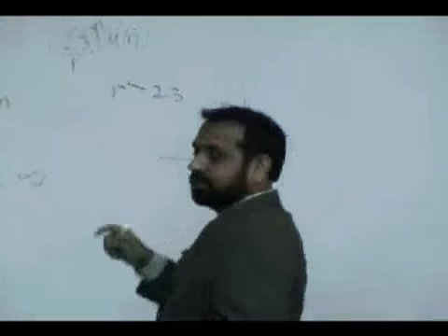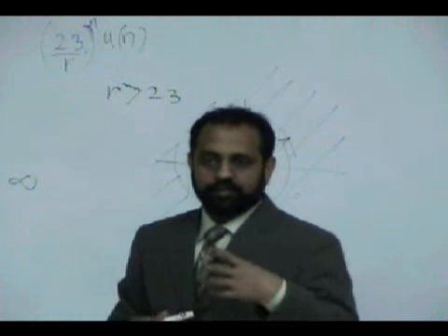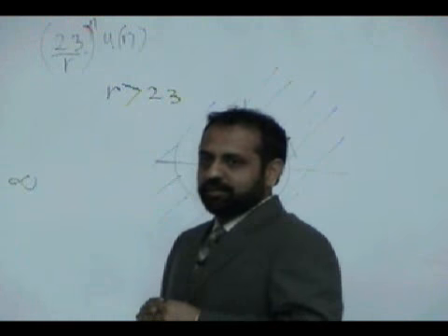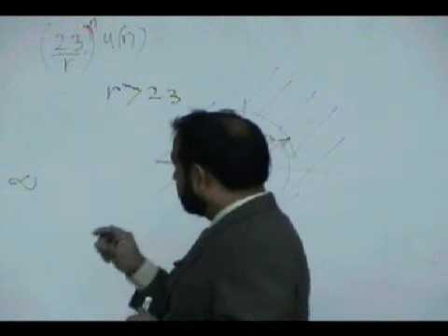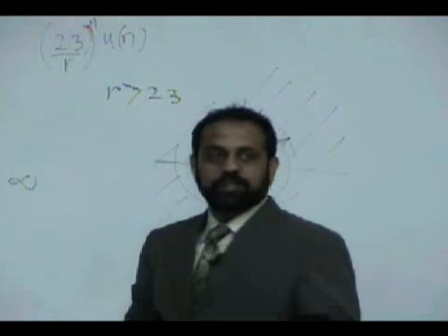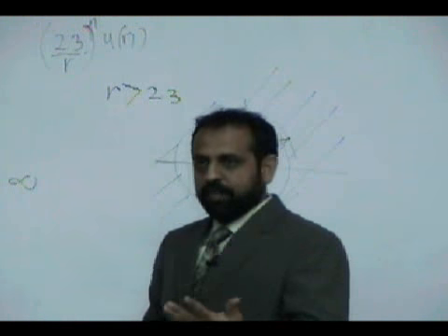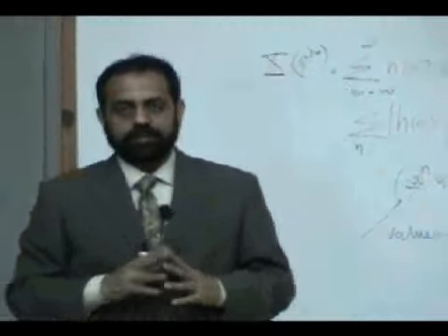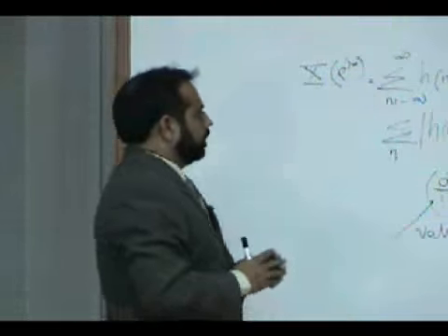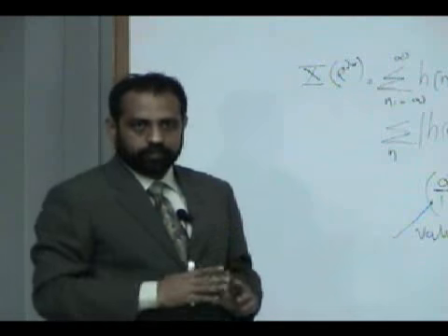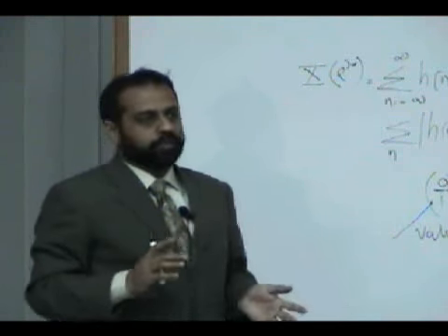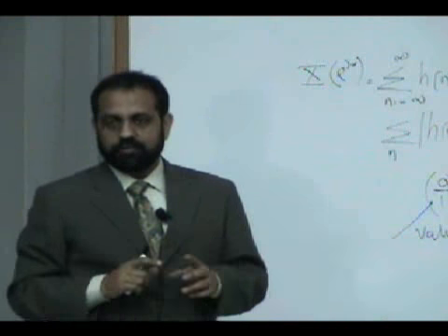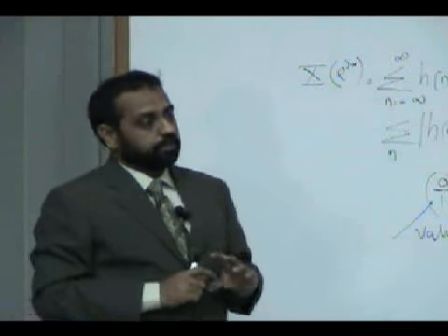By just looking at the sequence I can say it converges or diverges. You can say that if there is only one exponential, if the system is written in this form. But usually a system is written in a difference equation form, and in a difference equation you don't know the exponentials in there. So the Z transform is a transform which is used not to check the frequency contents but to check the stability of a system. Z transform is used to check whether a system is stable or not.